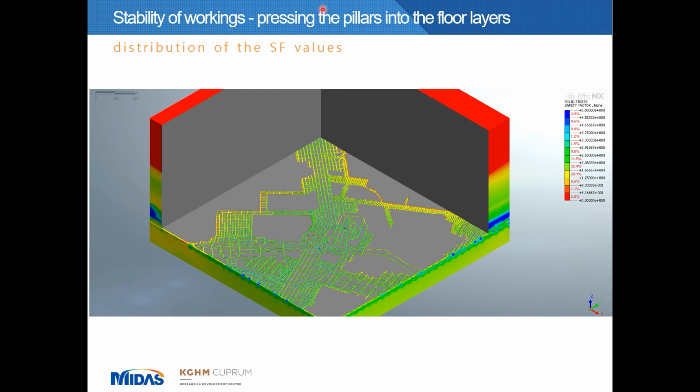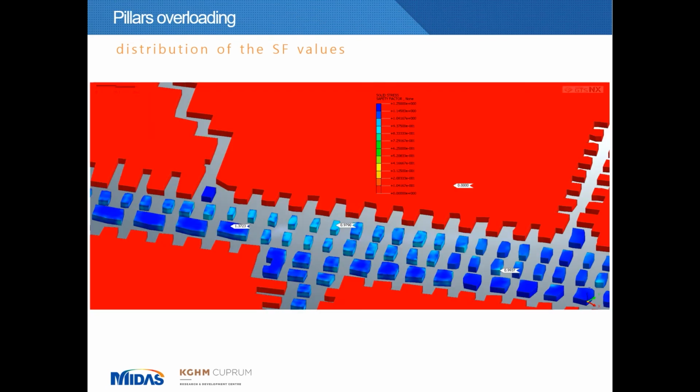Of course, near the gulf, there is an area of concentration of low safety factor values, and of course on the contours of the projected mining panel. However, this level is not so low as to indicate a potential threat. This situation is generally consistent with the observations performed in situ. Okay, and now going further, knowing that the floor layers should withstand the pressure of the pillars, of course with the designed geometry, we can proceed to the stability analysis of the pillars within the analyzed area.